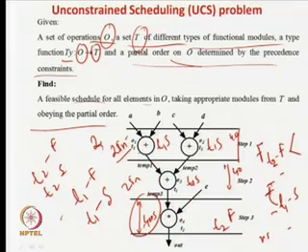Even if I have a very slow adder which will give my answer in, say, 30 nanoseconds, I will be prone to put that, because I cannot increase the time steps; they are fixed to 40. My motivation is to compute all my addition answers in less than or at most equal to 40 nanoseconds, using as little hardware as possible.